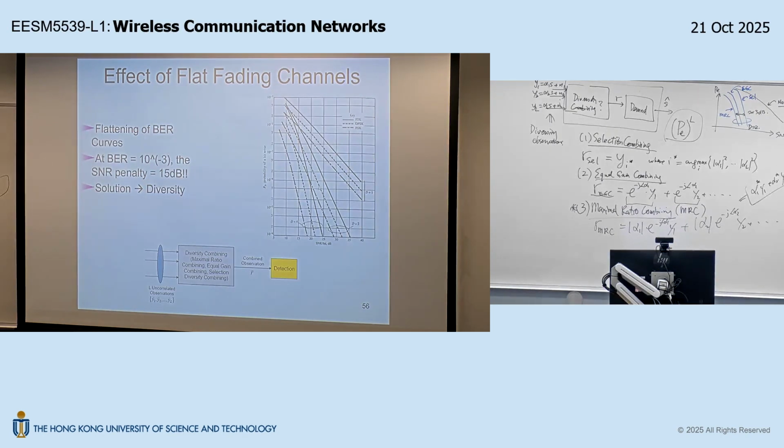The baseband uses this preamble observation to estimate the corresponding alpha. For example, if the switch is in the first position, then during this entire preamble period, the switch can only pass on the observation from the first receive antenna to the baseband. And if that's the case, the baseband can only estimate alpha 1 hat, right?